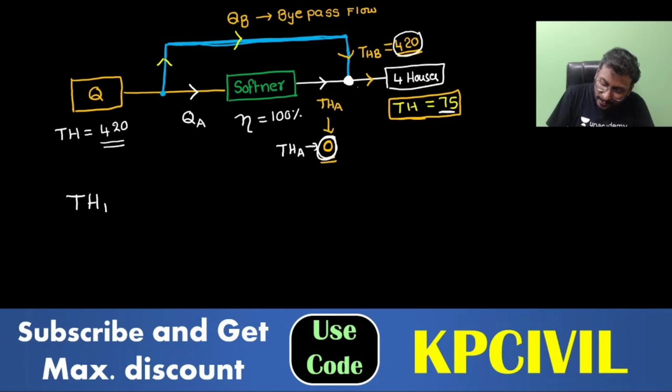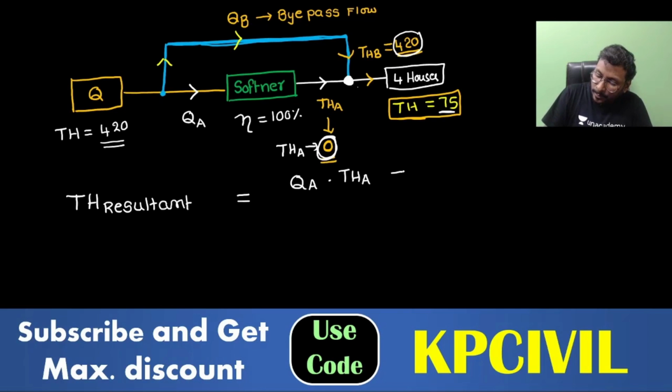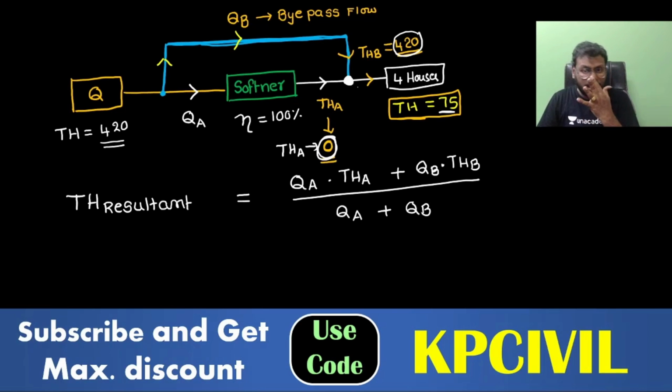So resultant total hardness, weighted average we can use here. THresultant is equal to QA into THA plus QB into THB, divided by QA plus QB. Weighted average we can apply here, is it not?